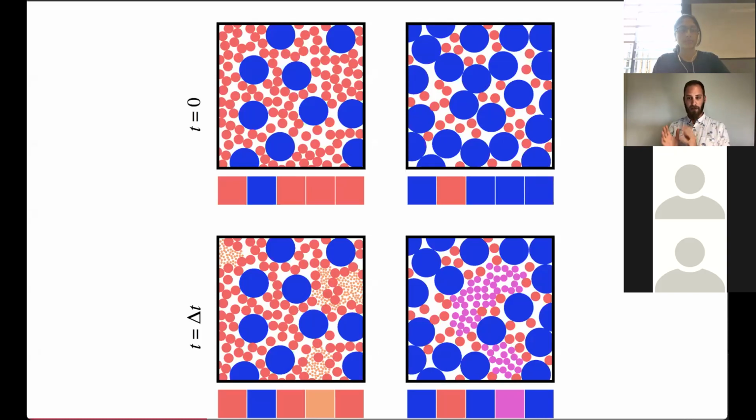And so that's half of the story. The other half of the story is that small particles, just by their very nature, are stronger. So you could imagine that you start off with a large rock, it's got cracks everywhere, and you carve out a nice large particle and it's still got the cracks in it. You carve out a small particle and it's still got the cracks in it. But because it's smaller, it's got fewer cracks in it. And so the net result is that this small one ends up being stronger than the large one. And so with these two mechanisms, we can decide which particle is going to crush for any given applied load.